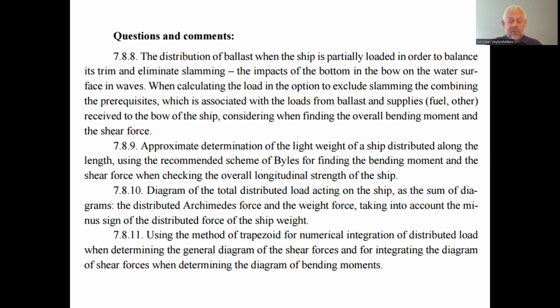7.8.11 Using the method of trapezoid for numerical integration of the distributed load when determining the general diagram of the shear forces, and integrating the diagram of shear force to get the general diagram of the bending moment. We use the differential interdependence of the distributed load, the transverse shearing forces, and the bending moments, because each next one is the integral of the previous.